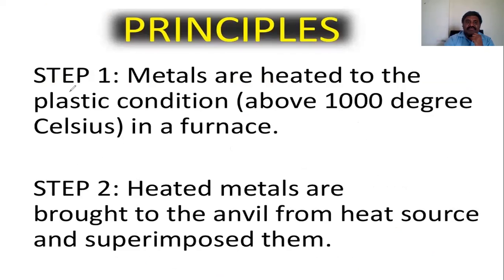So this is the principle. If I am saying, see here from the principle, metals are heated to a plastic condition, just above the recrystallization temperature and below the melting temperature. It is heated above 1,000 degrees Celsius in the furnace here.